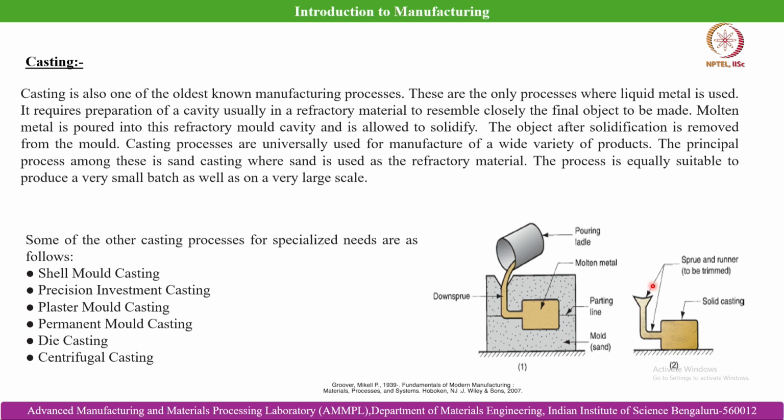In casting there are a couple of aspects. Number one is the material aspect, where you need to prepare the melt in an appropriate way so that it is free from defects, so that you can get sufficient structural integrity in the cast parts, and mechanical properties at the desired level.